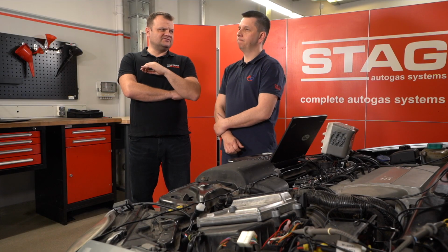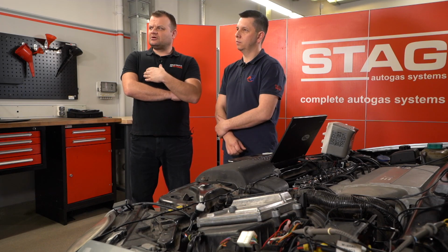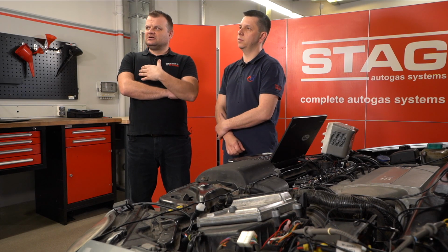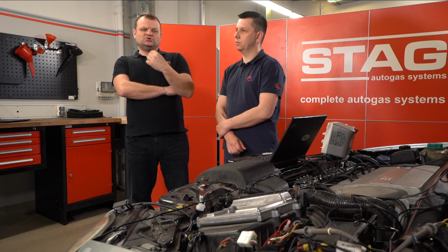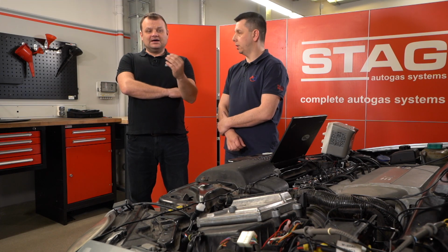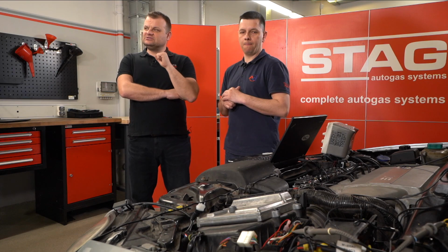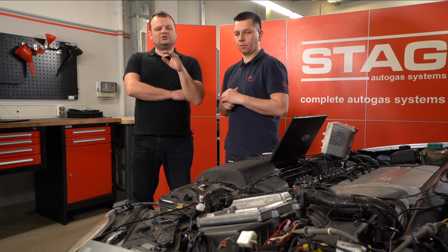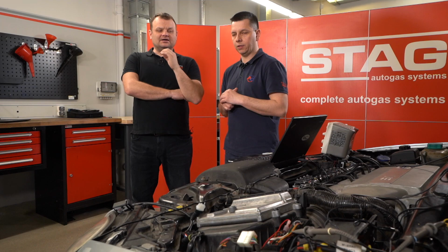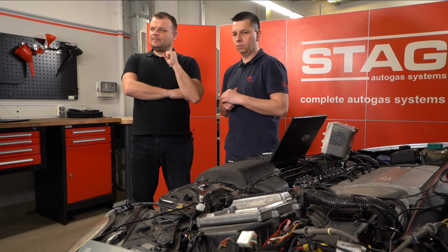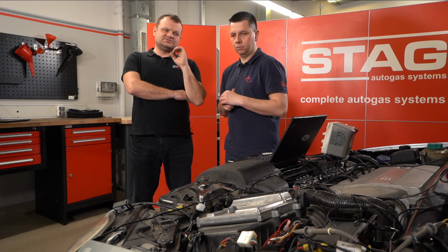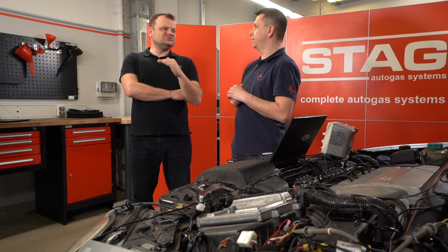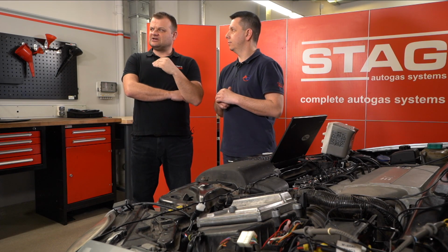Also, this car with this engine is included in the manual, but in some markets we can meet a different pinology of the petrol ECU, and then you're confused about which one to use. So you choose one pin or the second pin, connect the oscilloscope and see how the signal looks. So what should we do? We should connect the signal and start the engine. And then we will show you how the proper signal looks and what should happen with the signal while the engine is running on idle or the RPM rises.